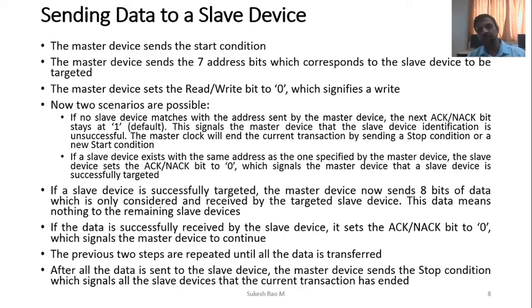In some cases it depends on the next addressing also, you can address in the same way. So consecutive memory devices inside the slave device can be addressed with a single start condition, addressing consecutively. You can keep sending the data, and it will write to the different registers. If you want to stop in between, send a stop condition. So that is the end of the protocol. Probably this can be clearly understood when you really implement an I2C communication protocol with a certain device.